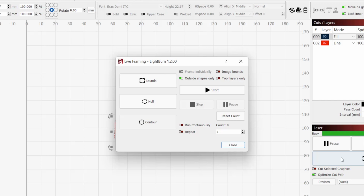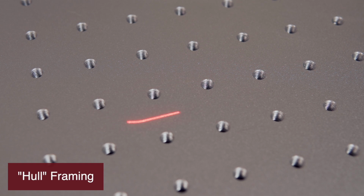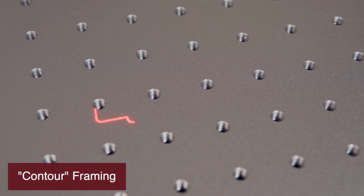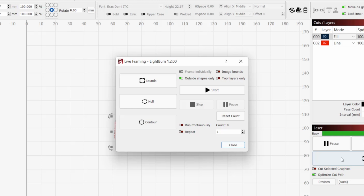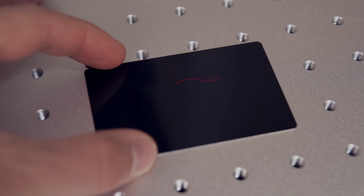With Galvo lasers, we have a few different framing options to choose from, which are bounds, hole, and contour. Bounds is a fairly standard rectangular frame. It will create a rectangle that fully contains the shapes that you will be sending to the laser. Hole, or rubber band frame, traces a path around your design that is the shape of a rubber band stretching around it. Lastly, there is contour, which will trace the walls of your design. The best framing settings to use will depend both on size and geometries of your specific project. We will be diving further into these framing modes in a future video, so stay tuned for that.